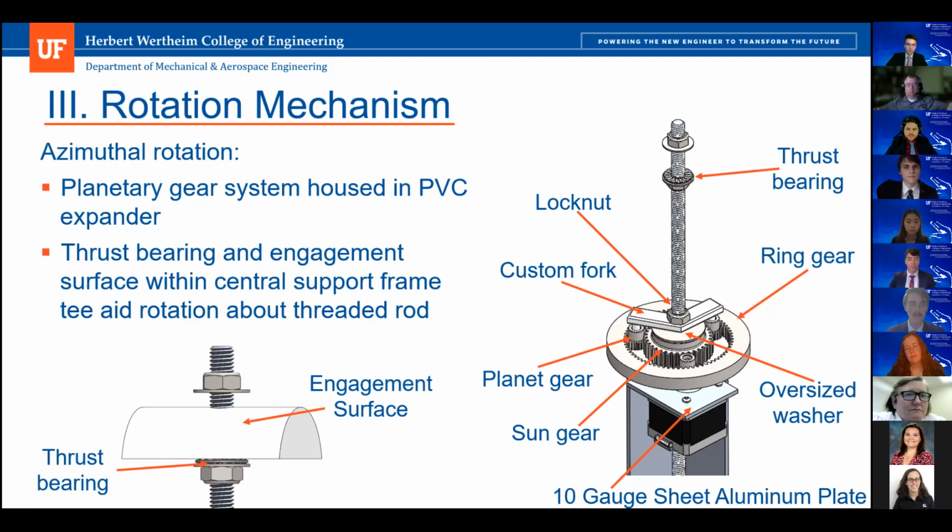Okay, are you concerned about that wearing out at all? We actually went through a redesign to prevent the metal from biting into the PVC over the 20-year period. That was one of the big redesigns. That's the whole reason that bearing engagement surface is up there. Originally, we didn't even have a bearing, but we wanted to prevent the 3/8 threaded rod from interfacing at all with our PVC frame, to prevent that biting. So that should be a lot less of a problem. Okay, thanks.